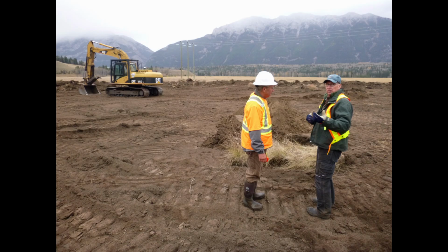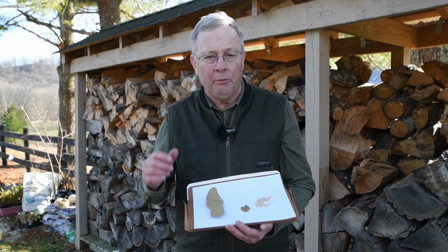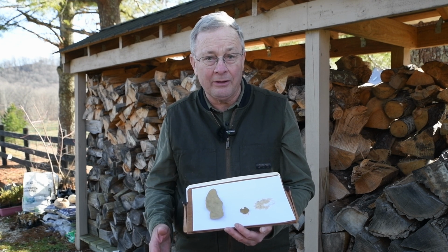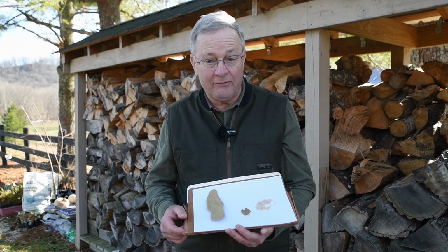Here I am with Rob Neal with the Nature Trust, who directed the wetland project at the Big Ranch. Rob died in 2023. It's very important to determine the texture of soil when you're designing a spillway for a wetland. This will help you decide how much rock is needed to protect the spillway from erosion.